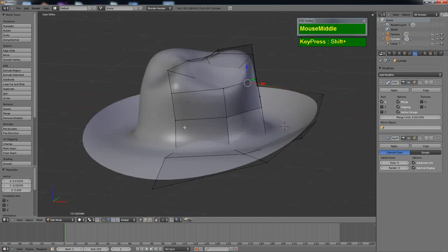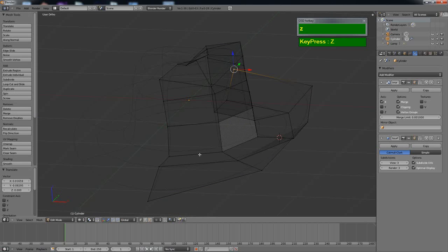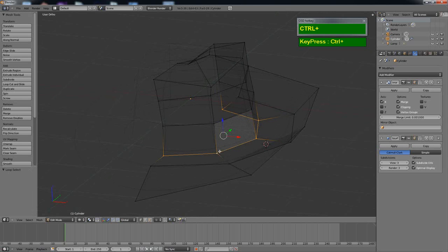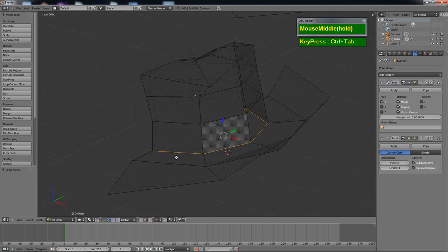You can use a function called creasing. Okay, go to wireframe mode. You can Alt right mouse click, select this edge. Let me convert this section to the edge. Control Tab, go to edge, and you can bring up an edge function called crease.